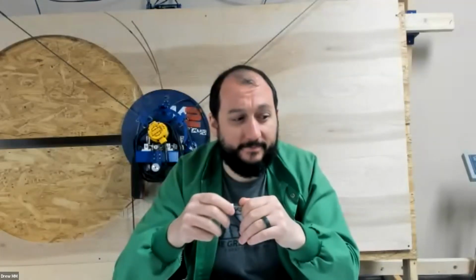Now, do you have a glass base, or some sort of polymer matte base? We have a mat that comes with it, but you can purchase any, like PEI, or you can put a glass sheet on there if you want. It's just a print surface that's made for PLA. The nice thing with the mats is they have some compliance. The problem with the glass is that it tends to distort, and the middle doesn't quite sit right.